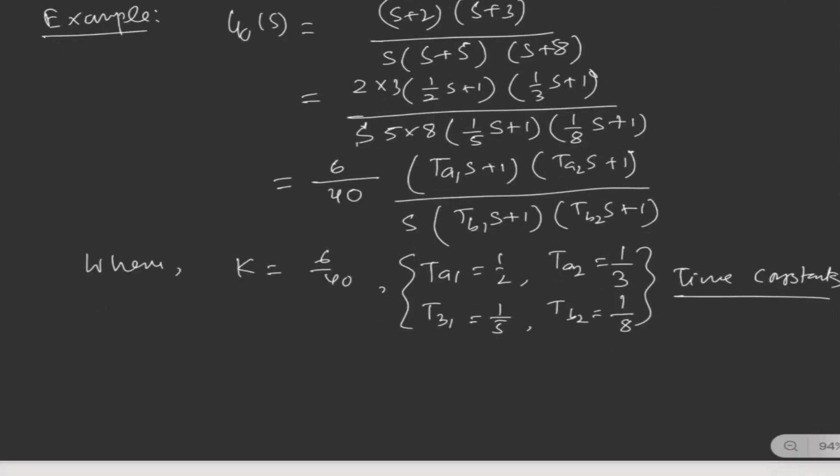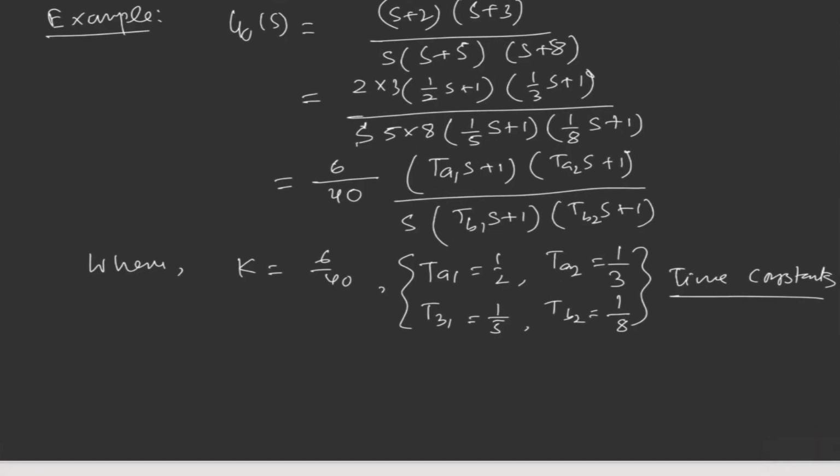In the closed loop system, while we are talking about the closed loop transfer function, what is the main motivation? Basically, we are making the system asymptotically stable, where all the poles of the characteristic equation of the closed loop transfer function should lie in the left hand plane.